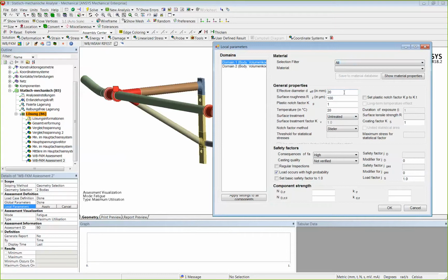So for the FEA calculation to get the stresses, I could go for any steel because Young's modulus and Poisson's ratio are the same, so the stresses will be the same. After that, I can still decide I want this steel, or I want another steel. So I can also check if I build it with this material, will it be okay, and if I build it with that material, will it also be okay? So I can make variants very, very fast.